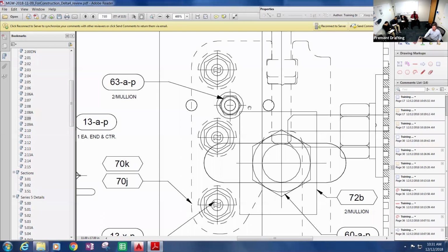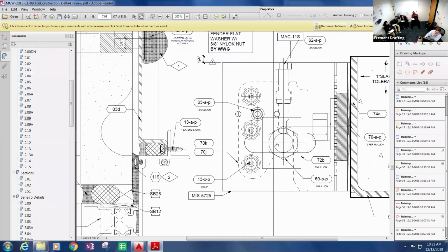Putting the pressure and the weight on that anchor bolt, that's a big 9-inch, 11-inch long bolt. If you take a tour of the shop and you see the hook lugs on the units, you'll see this bolt is pre-installed. There's a nut right here with a nylock washer on it, and that nut's held in place. Then the bolt, they can screw up and down to get their final adjustment to get the unit set in place.